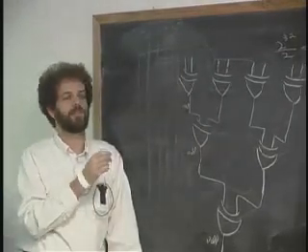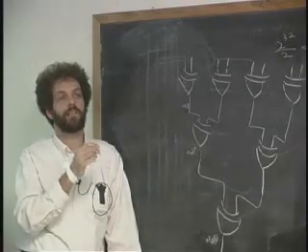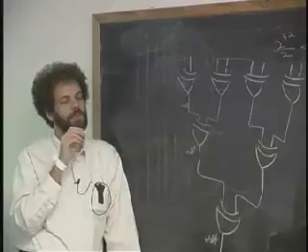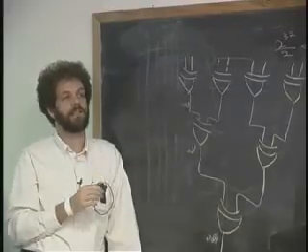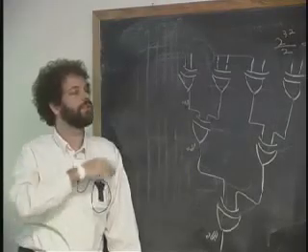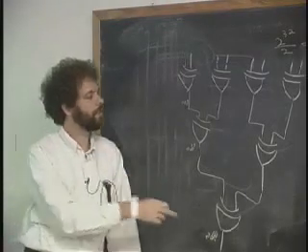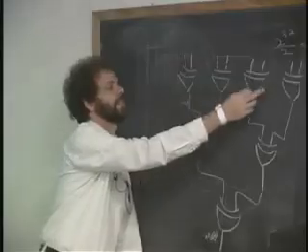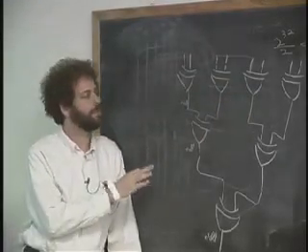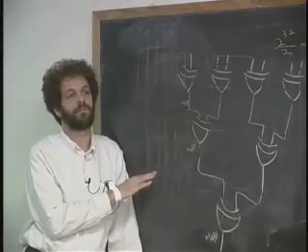Draw me the sum of product of 8 inputs. 2 to the 8 is 64, right? So I'm going to have 32 AND gates and an OR gate with 32 inputs, which is a huge structure compared to this one with 1, 2, 3, 4, 5, 6, 7 parts in it. Much smaller and much faster too.